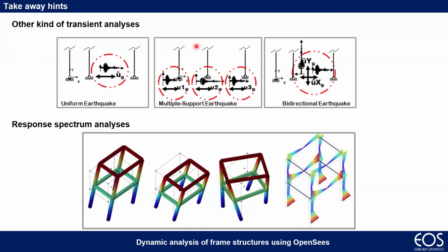Yeah. Go ahead. The question is, if I am doing an analysis, let's suppose for a structure which has a pile foundation, and I am modeling the piles, providing equal DOF and zero length elements for soil stiffnesses and all, then when I want to perform multi-support excitation or uniform earthquake excitation, how should I apply it to the model?